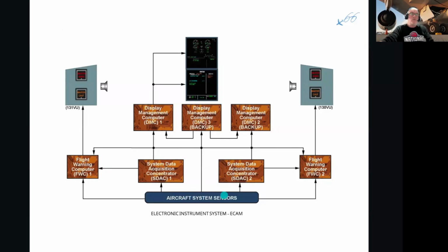So all these units of information coming in, altitude in feet or in meters, fuel in pounds or kilos, the time, the angle of attack sensors, every single bit of information is coming in its own particular unit. When it leaves these two boxes, it goes into ones and zeros, which the computers can process. These computers here process these signals into a video signal and put the information up onto these screens. And that's how it works.